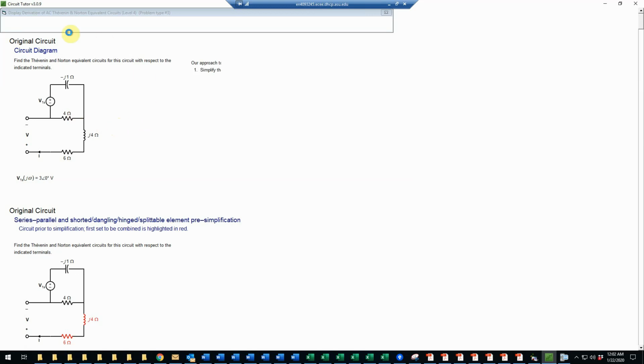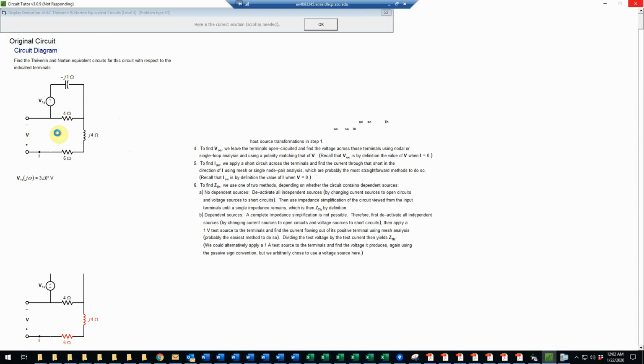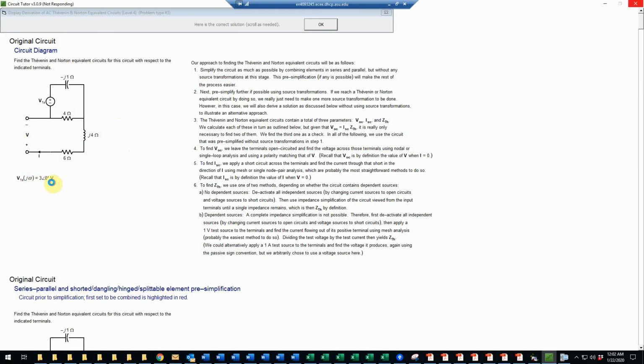So you can see we are being given a problem here in the phasor domain, as we have complex impedances and phasor values for the voltage source. And this has a set of terminals which are going to be used to connect to some arbitrary circuit. And we have labeled on there an output voltage V with the indicated polarity and an output current I with a corresponding polarity that constitutes the active sign convention with regard to whatever is going to be connected there.